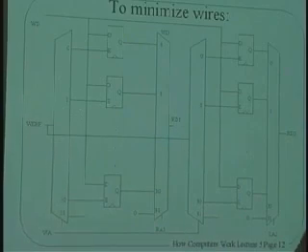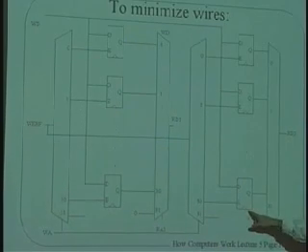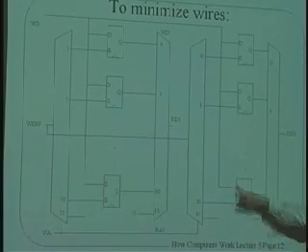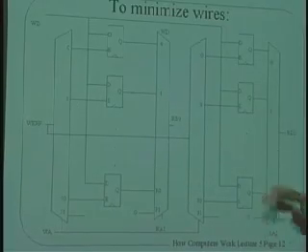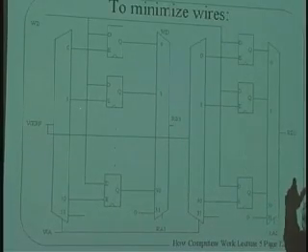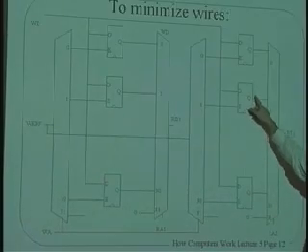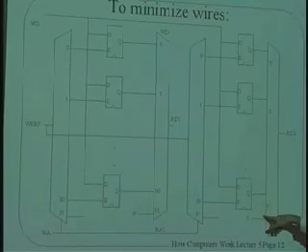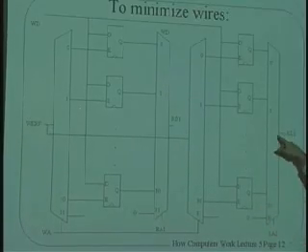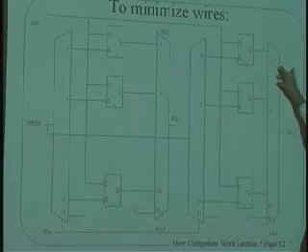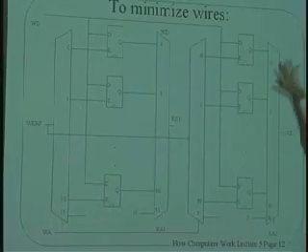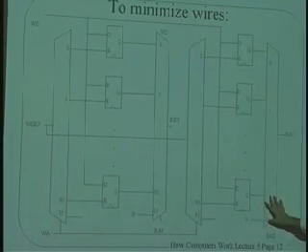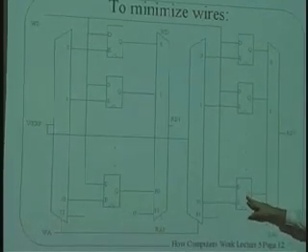And in particular, it turns out that the circuitry involved in building this, guess which takes more circuitry? To store the bits or to select the bits? Now, you'd obviously think, oh my God, building a memory is a hard thing, right? But actually building the selector is harder. This is this big tree structure that says, okay, if it's one of these two bits, we choose these, then we choose these, we choose these. You get this huge tree here, and this one actually takes up most of the transistors on the chip, and this takes up very, very little.